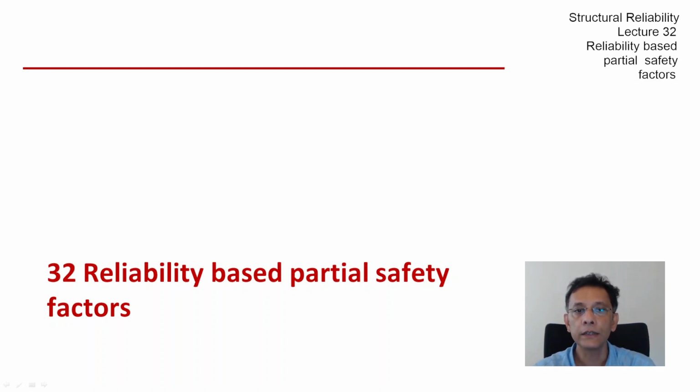The design load effect is compared with the design resistance. The design resistance is the nominal resistance multiplied by a resistance factor. The nominal resistance for the failure mode in question is computed with the help of characteristic material properties, which in turn have been modified by material partial factors. In LRFD, load and resistance factor design, the material partial factors are not separately specified. Now, all these factors are designed to achieve a specified minimum reliability in design, at least, as we'll see later, in an average sense.